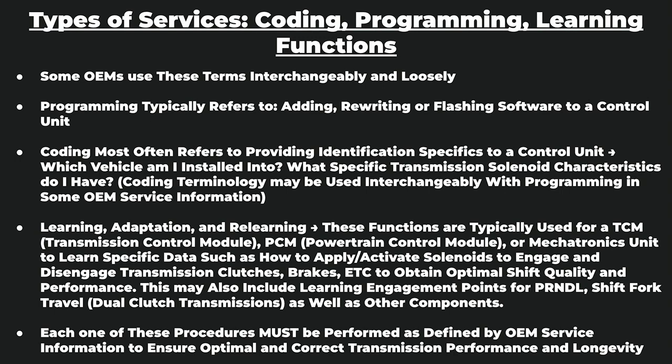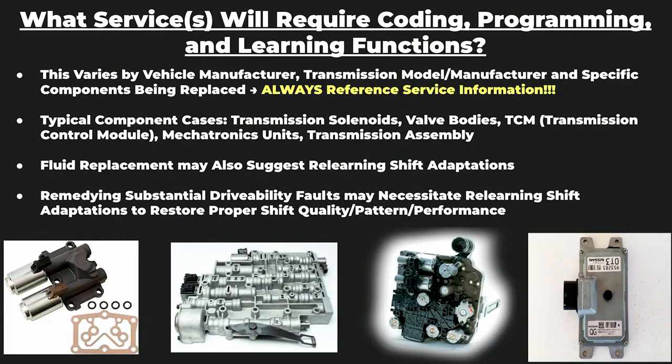Again, anything related to engagement of park, reverse, neutral, drive. That's important for the transmission to learn those shift positions from the shifter and modulate its behavior based on the shift position. So again, it's really crucial we understand when these have to be performed and that we remember to perform them. So here are some examples of when you might see these types of procedures triggered or needed depending on each individual vehicle. Again, we always want to look at service information in order to be certain what is required for the given vehicle.